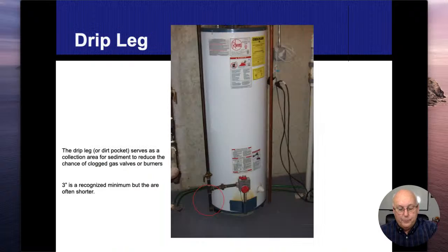Drip legs, we talked a little bit about it already. Anytime I have a drop, we want to give a place for the sediment. If there's any oils or moisture or anything in there, we want to give that a place to collect so it doesn't come into the gas valve and damage our gas valve.